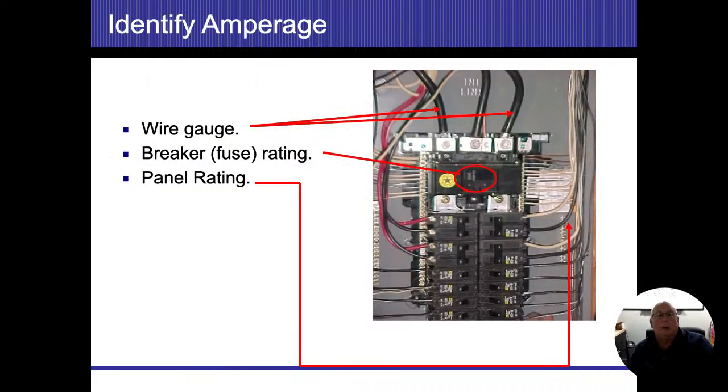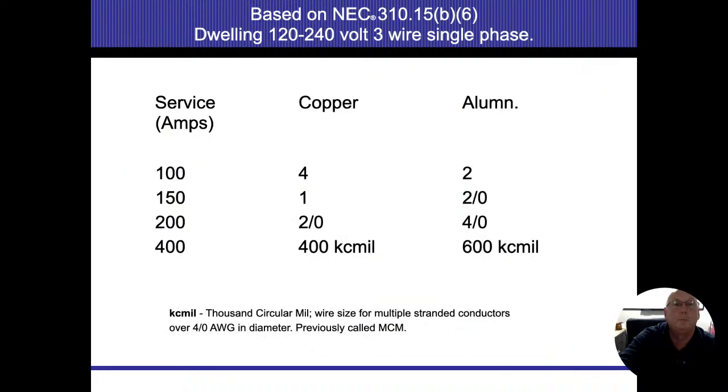All right. Wire gauge is going to be our next thing. We went through it before. So typically we're going to either see a number 6 feeder coming in there. That's going to be for 60 amps. A number 2 aluminum or a number 3 copper, and these do need to be committed to memory, those are what we're going to see for 100 amps. And then we're going to be dealing with 2-aught copper, most likely for 200 amps where it comes into it. And that's what they're showing here. So I know it says number 4. That is what the NEC calls for. But very common in the Chicagoland area, we're going to see number 3 coppers.